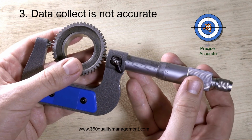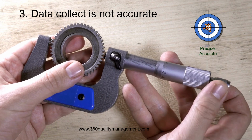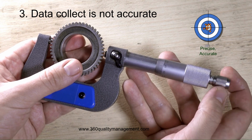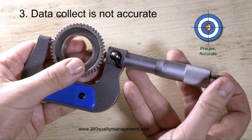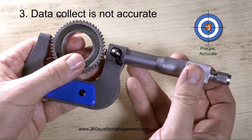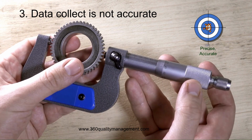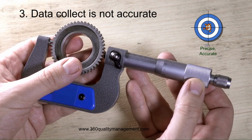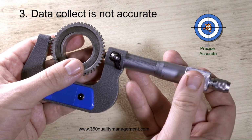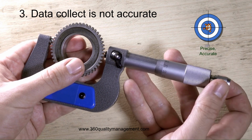Mistake number 3. Measurement is a process to collect data which is used to plot the chart, and it has a variation on its own. Sometimes the same operator measures the same part a few times and gets different readings, which by right should be the same reading in the best case scenario. It could also be that different operators measuring the same part get different readings, which gives a variation where we also want the same reading.